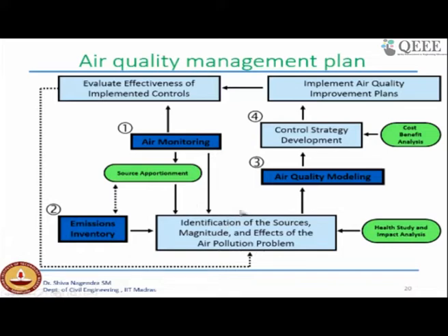So based on your measurements, you will be able to understand which source is contributing pollutants in that particular area. You can also use information related to health. Suppose you have health data, and you notice respiratory illness, skin allergy or high irritations, you can link which type of pollutant is causing it, either oxides of nitrogen or sulfur dioxide.